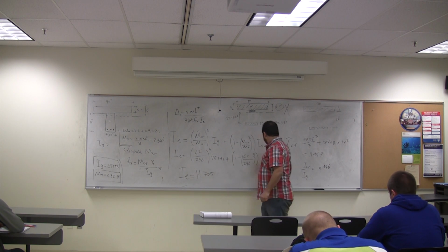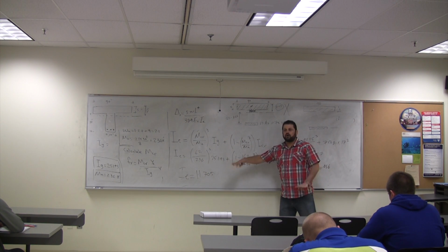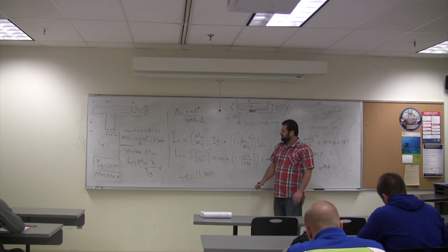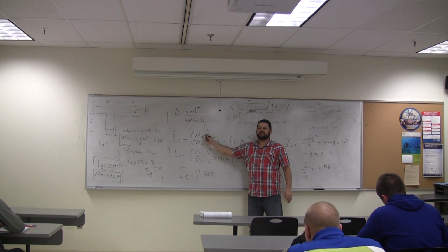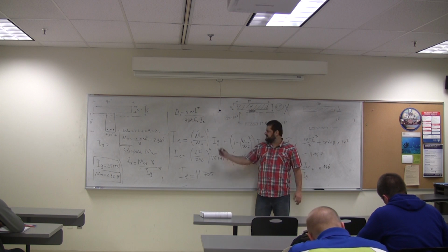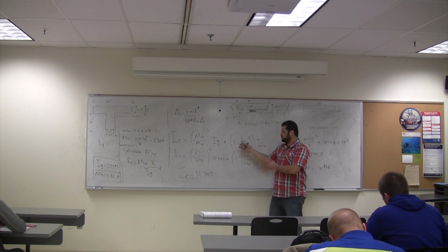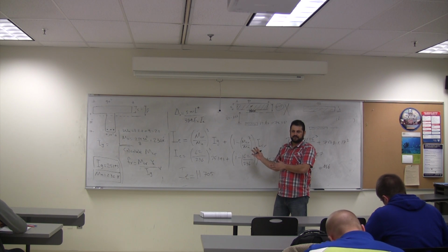So, for your reference, I effective is always bigger than I crack. It's very close to I crack. You know why? Because usually this ratio here is very small. So this factor, when multiplied by I gross, is a small factor compared with what you have in here.